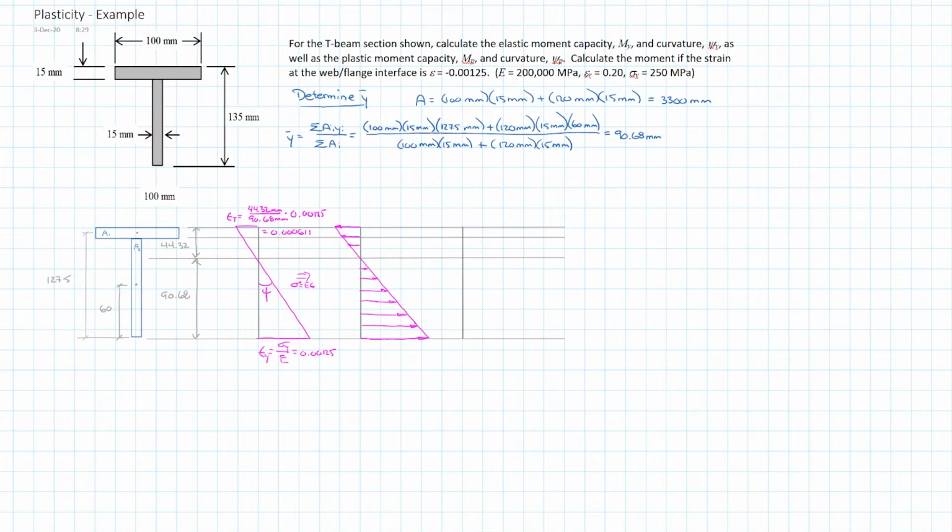Now, because of the relationship of Hooke's law and this being epsilon y, then this is also sigma y, or 250 megapascals, which will occur down here. Of course, it occurs at the bottom where the maximum strain is, and by definition, we know that this is the point at which we reach 250 megapascals, or a strain of 0.00125.